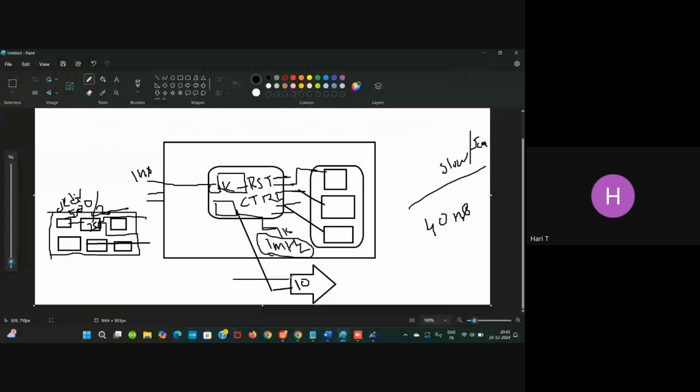We can connect I1 to suitable clock frequencies like the scan clock. We will have a separate hierarchy where all these scan pins get entered. We can bring out this connection like this. Sorry, this is a scan clock, suitable clock. And the selector line is the scan mode.